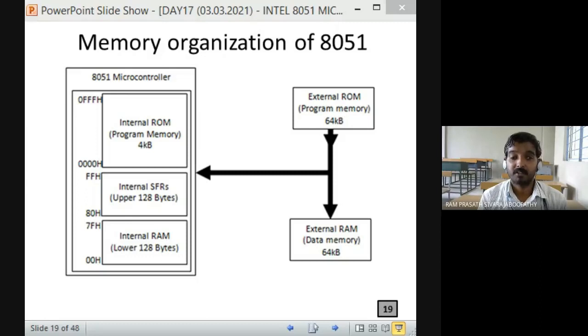Correct? So generally I have a 16 bit address. In Intel 8051 microcontroller, there is a 16 bit address space for program memory. So there is no doubt in that. Fine. But for the on-chip ROM, to know how the address range becomes 0FFF, the maximum on-chip ROM size is 4 KB. That means 12 bit address.